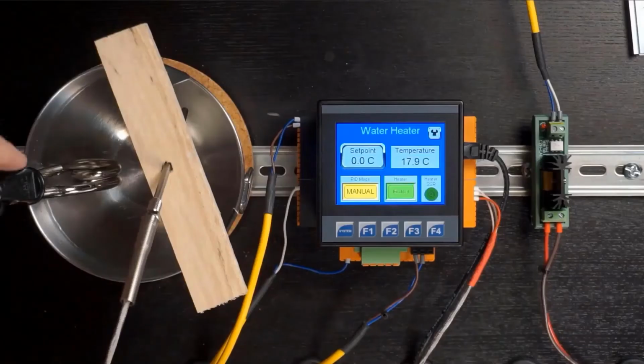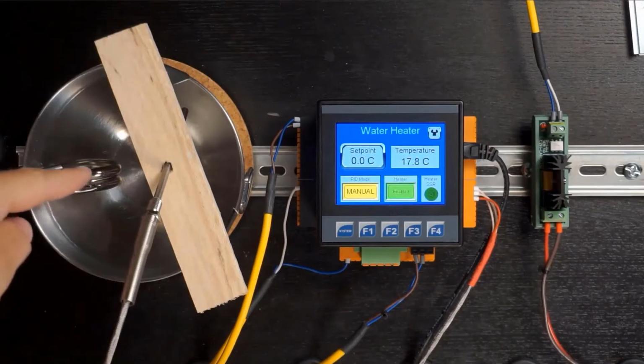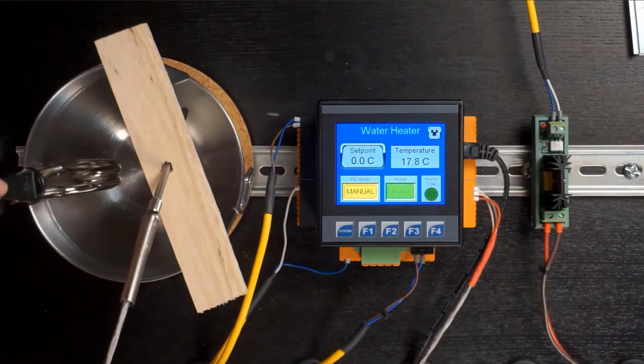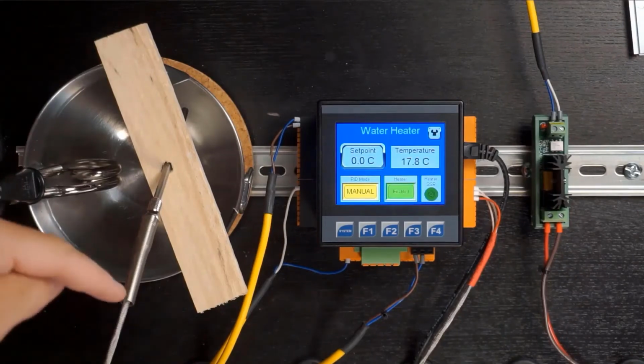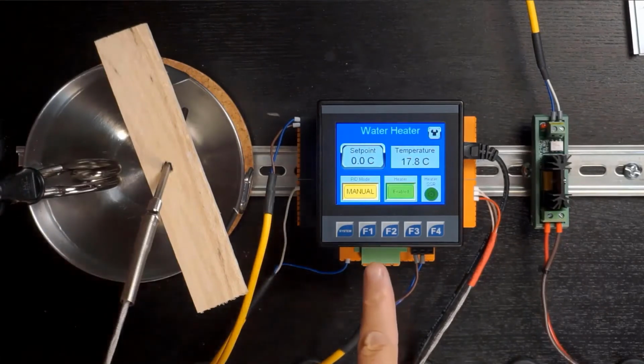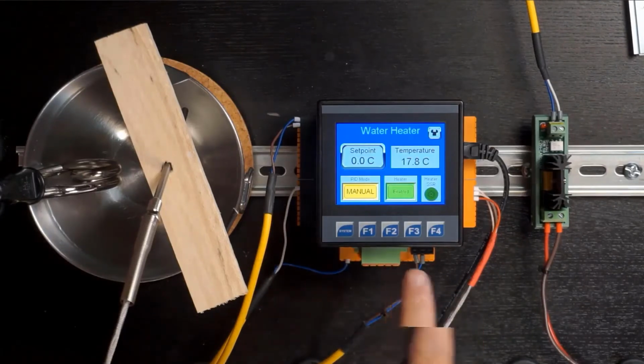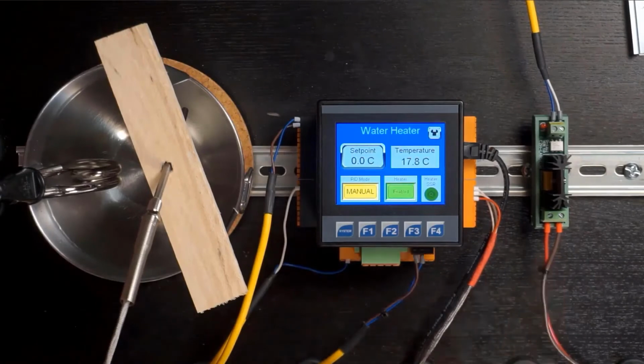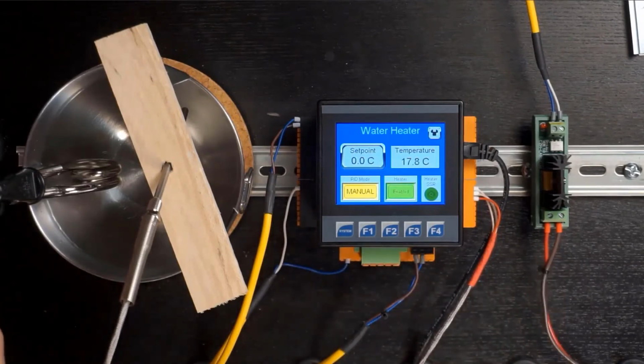So here's my test setup for our PID tuning experiment. I have a bowl with half a litre of water in it. I'm going to heat the water. I have an immersion heater here, and I have an RTD probe that's measuring the temperature of the water. I'll be executing the PID on the XL4. We'll use an on-off control or a digital output from the PID loop. That will run through a solid-state relay that is controlling the heater. So let's look at how we set that up in Cscape.